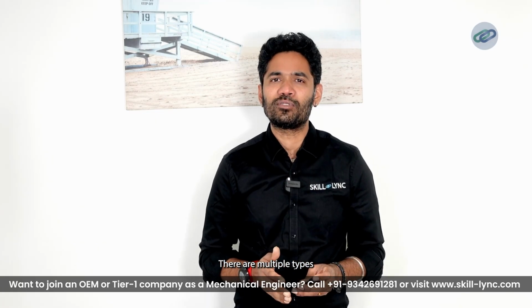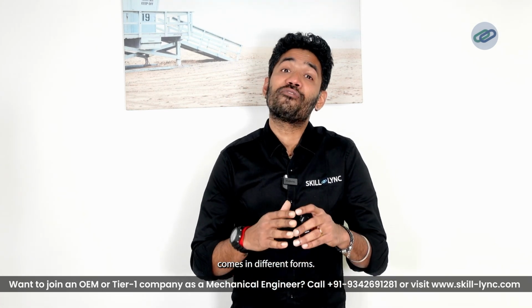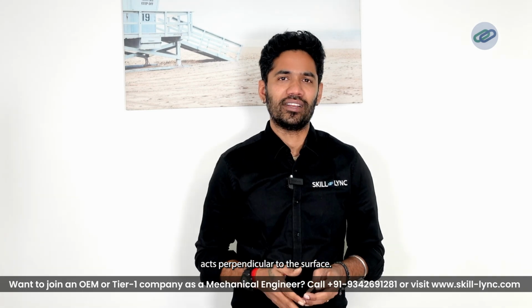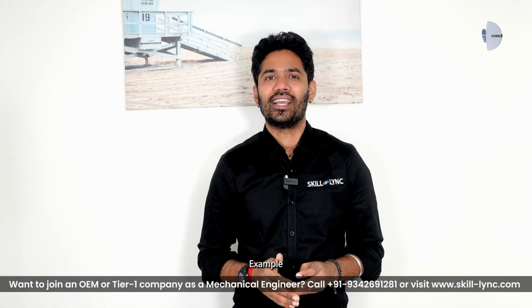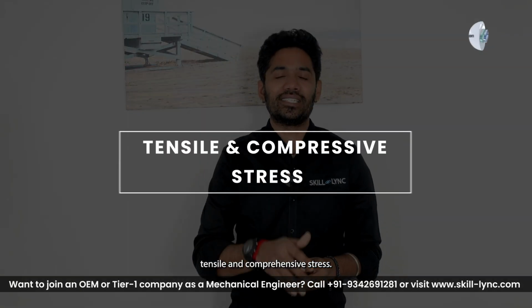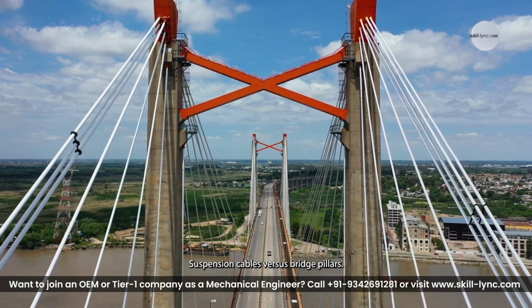There are multiple types of stress and pressure. Both the stress and pressure come in different forms. Normal stress acts perpendicular to the surface. Example, the car chassis under a load. Shear stress acts parallel to the surface. Example, cutting forces in machining. Tensile and compressive stress are the stretching or squeezing forces. Example, suspension cables versus bridge pillars.